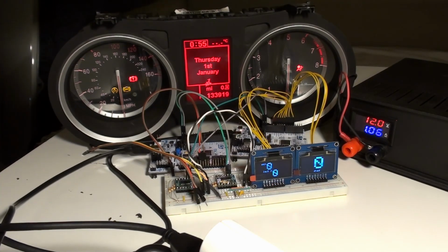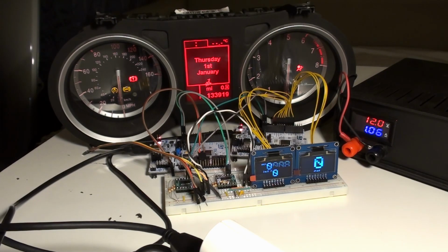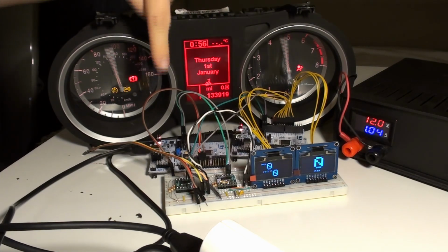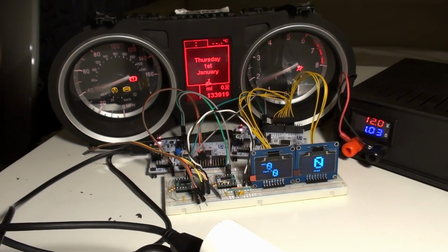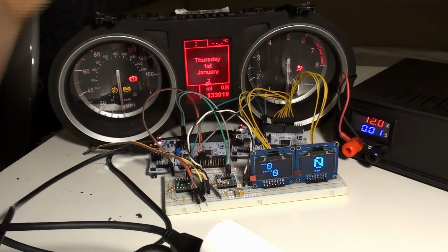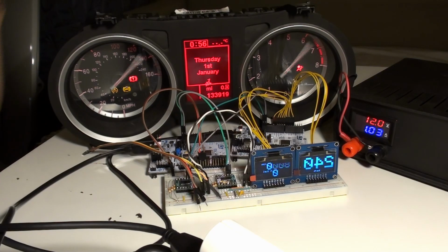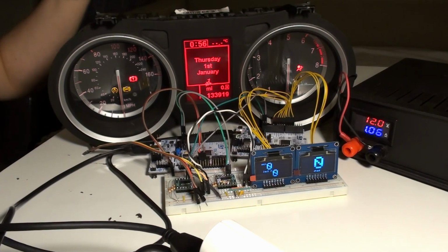So here I'm sending 240 kilometers an hour and 8,000 RPM, and that's why the needle sweeps, and that's how I know that I'm sending the correct frames with this test Nucleo, and that I'm going to be reading the correct frames in the car. And this is an Alfa gauge cluster, not a Fiat cluster, but fortunately both of those cars from about 15 years ago utilize the same network architecture, the same CAN buses and so on, and that's why it works. The protocol, as we can see, is the same because it works.